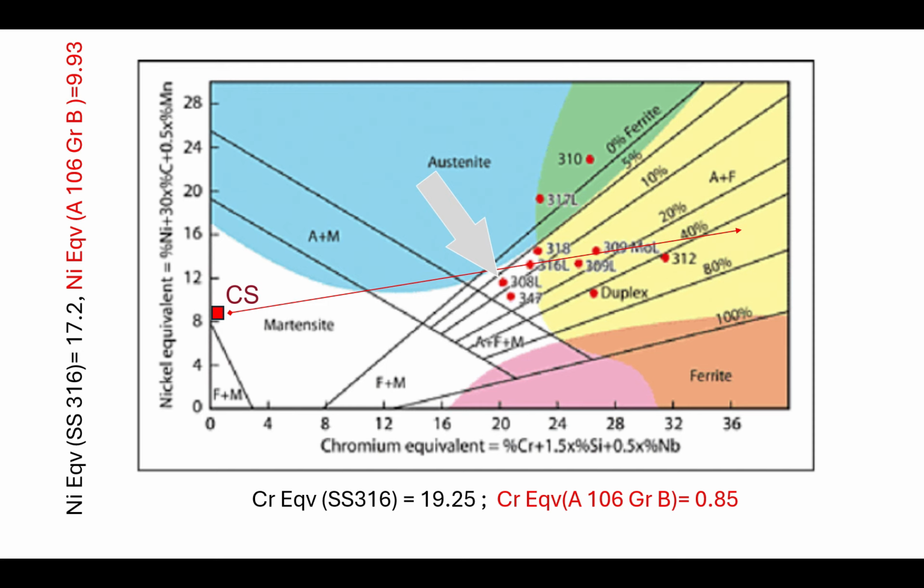Very interesting. Now, if a steel does not have any ferrite content in it, it becomes prone to fissures or micro cracks. So 5 to 10% delta ferrite is highly desirable. If you look at 316, it has 8 to 10% ferrite content, which is highly desirable.